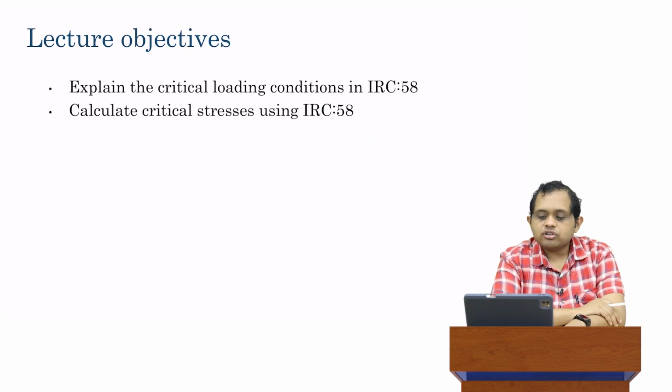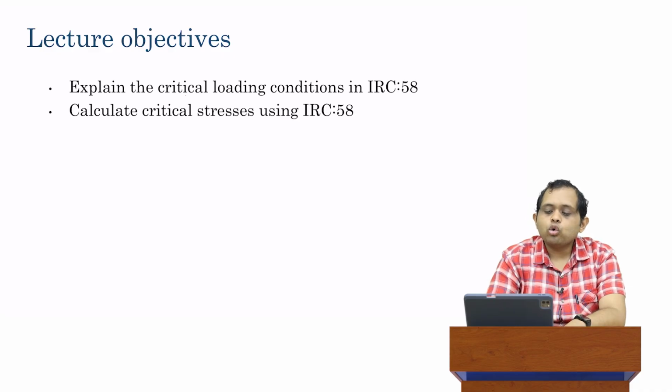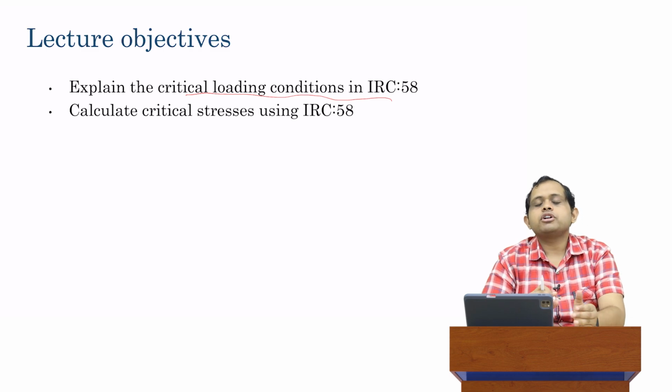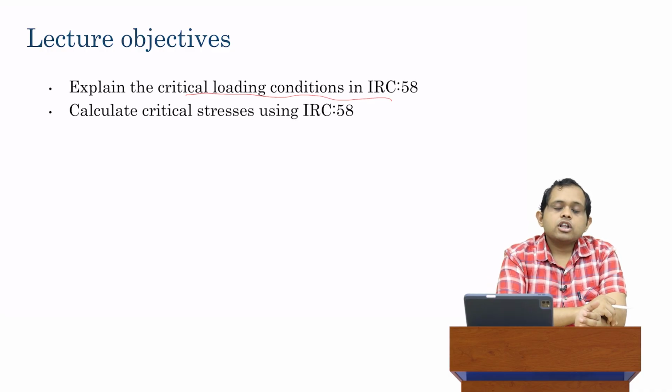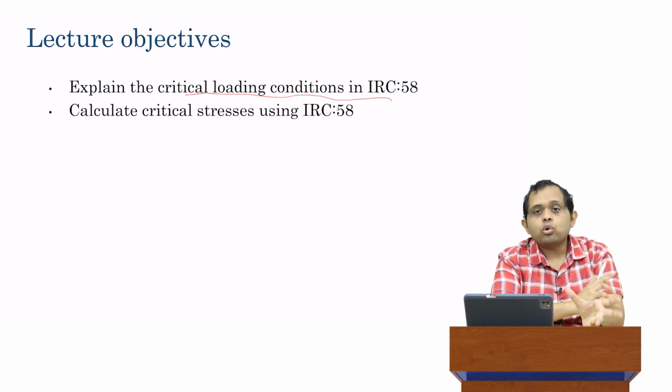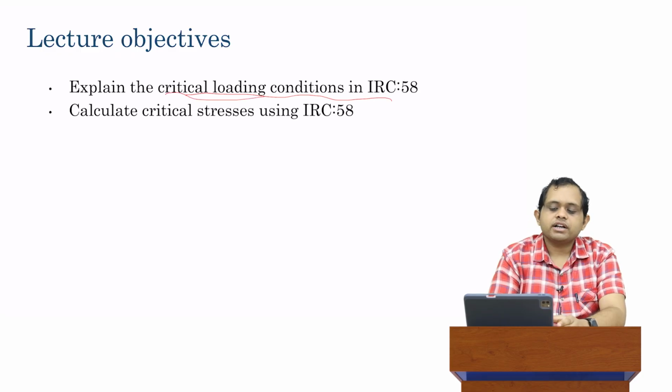So the aim of today's lecture is I'm going to explain what are the critical loading conditions. So remember, when you're looking at a finite element model, your stresses which are developed, of course, I already mentioned they depend on the material, they depend on the thickness, etc. But they also depend on where you put the load. Depending on the position of your load, you can develop different stresses. So it's not just important to understand how to calculate stresses. It's also important to understand from a design perspective, where should you put the loading such that you're going to get the maximum stresses. And that's what we call critical loading conditions.